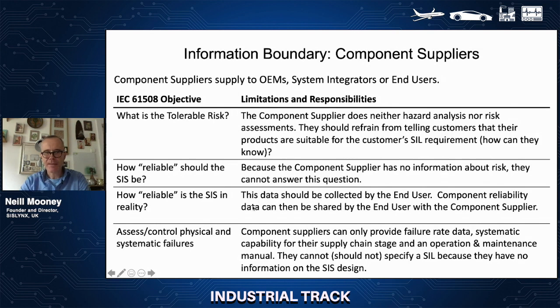How reliable is the SIS in reality? This data should be collected by the end user once the SIS is operational. That data can then be shared further up the supply chain. An assessment and control of physical and systematic failures: all the component supplier can do is provide failure rate data, systematic capability, and an operation and maintenance manual.